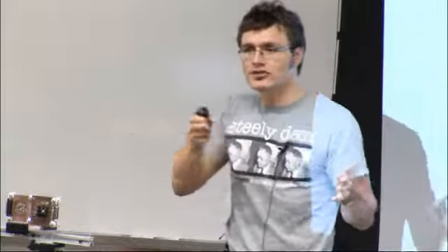There are many ways to do beamforming, but two opposing extremes are the minimum variance distortionless response beamformer, it's not important what it really is, and delay and sum. They're different in the following way. MVDR is great if your system is perfectly calibrated, and then it gives you the best possible beam. But if your calibration is imperfect, then it could perform worse than a very simple beamformer, delay and sum, which turns out to be the most robust to manufacturing tolerances. So we lean towards the delay and sum beamformer because, unfortunately, we don't have excellent calibration of our device, even if we wanted to have it. We tried.